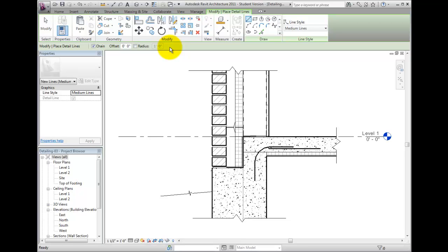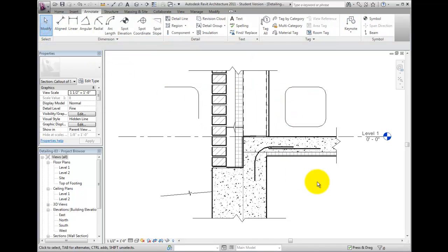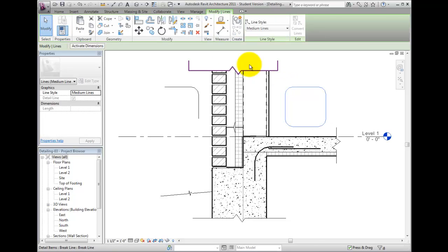Let's explore this a little bit closer. Normally, you will see this when you are creating curved sketches, or with tools like Polygon when it is based on a circle. If I am sketching straight lines, enabling the radius allows me to automatically fillet the corner. If I choose the rectangle tool and select the radius option, it will fillet all four corners. This is just a quick shortcut to drawing straight segments, then later going back and using the fillet segment.